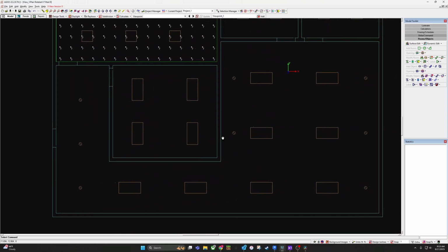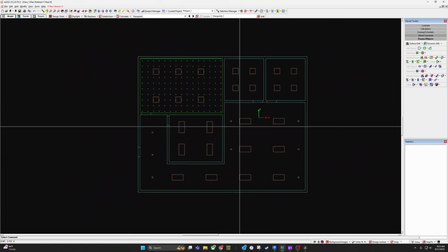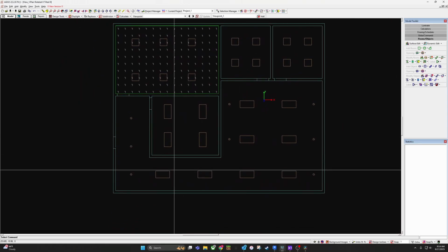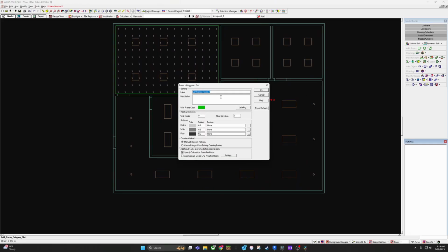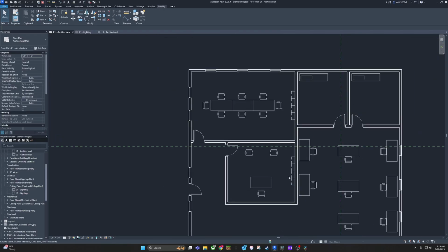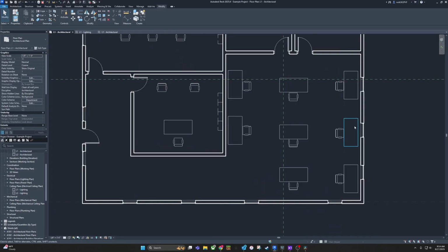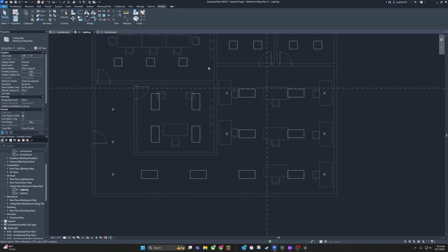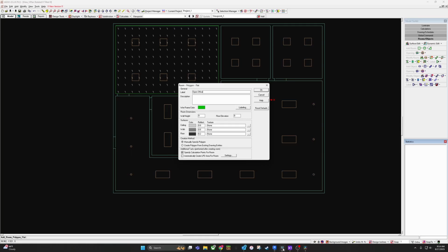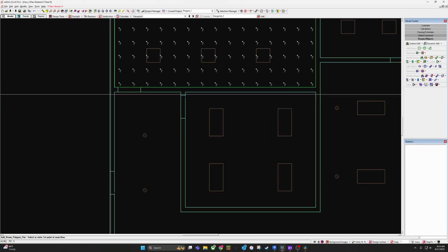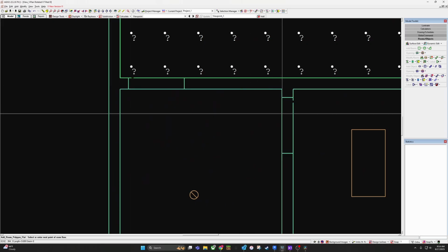Let's go ahead and do one. Let's go and do this space now. Want to create a room here? You should use polygonal. Call this open office. And here, hallway, office space. Boom. Open office, 9 feet tall. These are the correct reflectances. Let's begin.